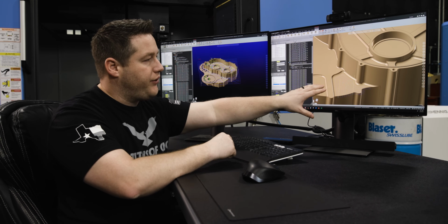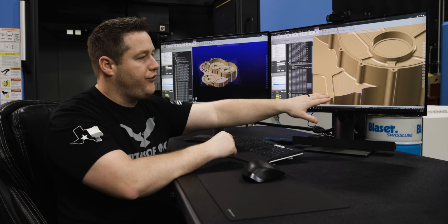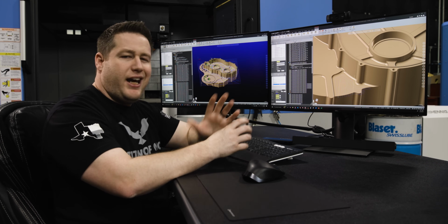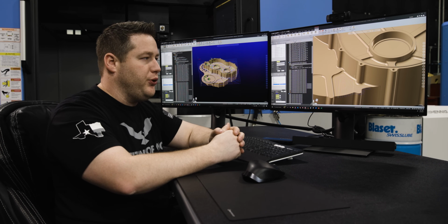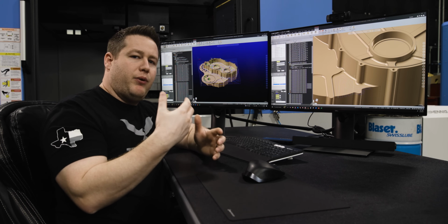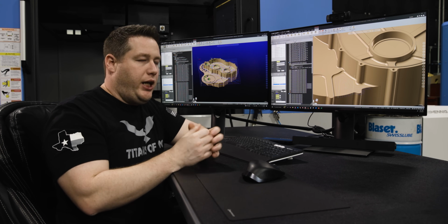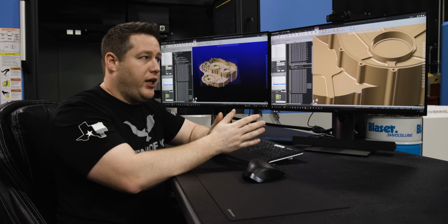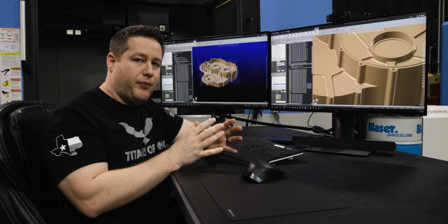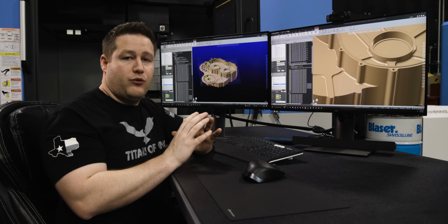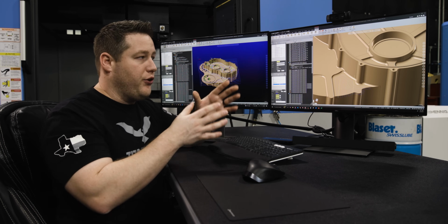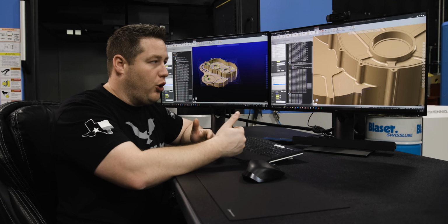All right, so now that's calculated, and you can see I've got a much better output. It's not gouging into my wall. And that wasn't that hard of a change to do. But when I sent this to Jay over at CloudNC, he was actually very alarmed that it actually gouged the part, because he said typically if you've got a good model and a good setup, CloudNC will not gouge your part. It's actually very hard to make it gouge. So the fact that it was doing that was pretty alarming.